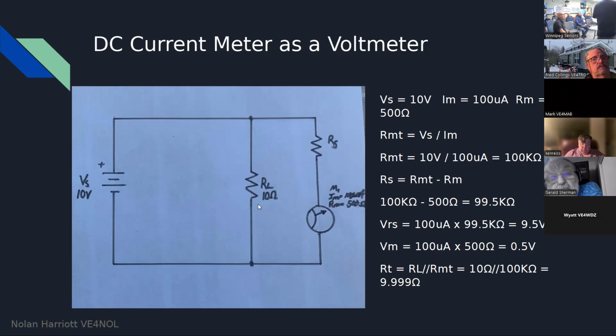Well, the meters will tell you that. There'll be a data sheet on it when you get them. So in the case of voltmeters, you want a really, really high resistance in your voltmeter. The lower the resistance, the more it's going to influence the resistor that's in parallel with it. Whereas in a current meter, you want the opposite. You want a really, really low shunt resistance because the higher that gets, the more it increases your circuit resistance, and the more it's going to reduce the actual current flow through your circuit. It'll be a specification on the meter.